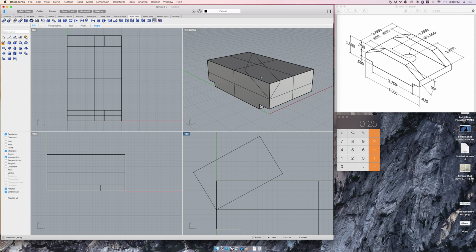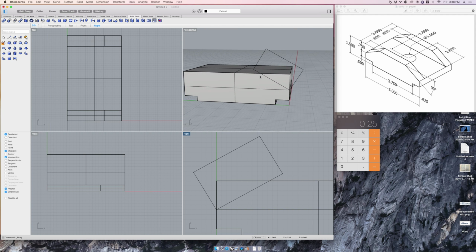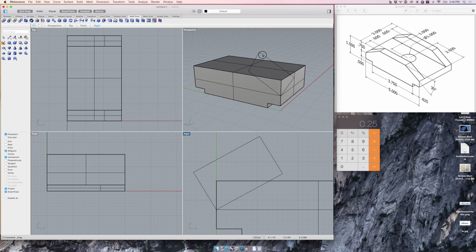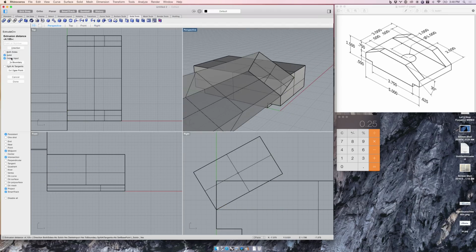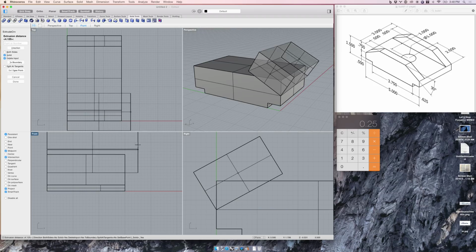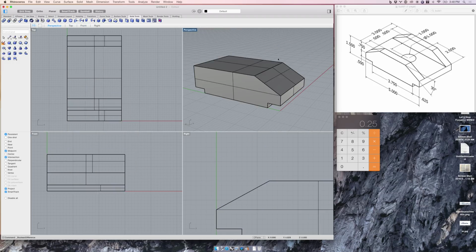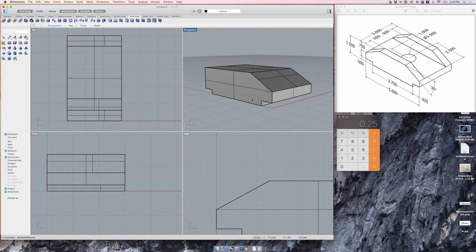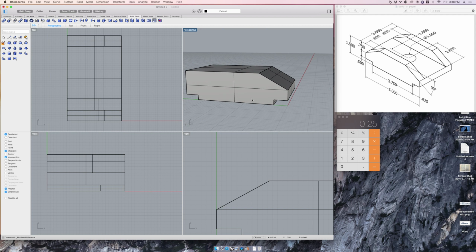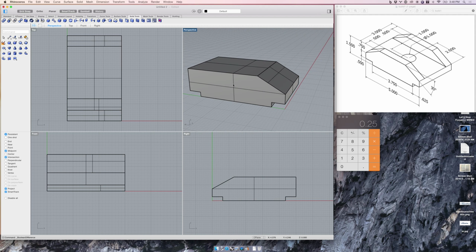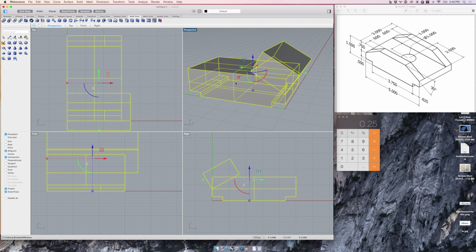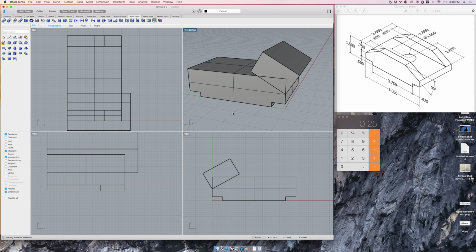Now, I'm sure you've already figured out what it is that I'm doing with this thing, but I'm going to now take this thing, make a solid out of it, and I'm going to extrude it and do a Boolean difference, right? Just like I did before, and delete that from the side. Now, I went a little fast there. It would have made sense for me to actually recreate that rectangle, rotate to the other side, maybe do a little bit of mirror. I'm going to go ahead and try right now and see if I can mirror some features. So I'm going to back up a step before I did my Boolean difference.